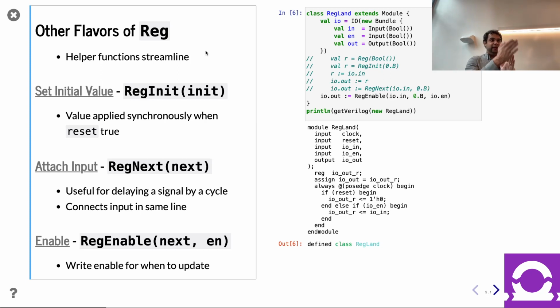The one corner case where they decided we really need an exception is asynchronous reset. It turns out in a lot of industrial designs and real chips, there are still synchronously updated registers, still synchronous edge-triggered flip-flops. However, their reset is asynchronous. There's a few reasons for that. Number one, if you have registers involved in bringing up your entire chip when it's first turning on, you may not have a clock yet. You may even need these registers to make the clock. And so having registers that can reset asynchronously is important.